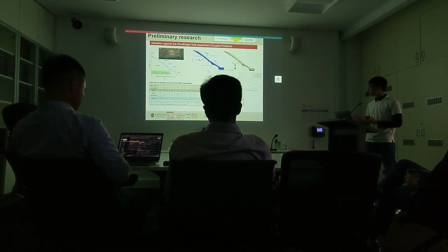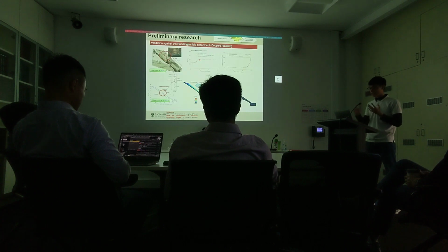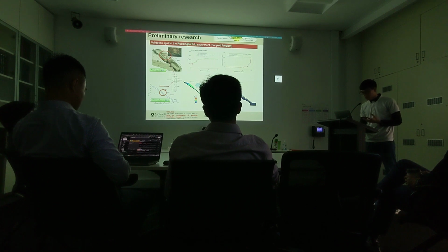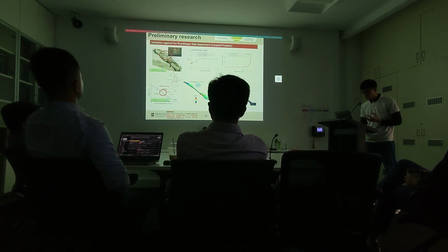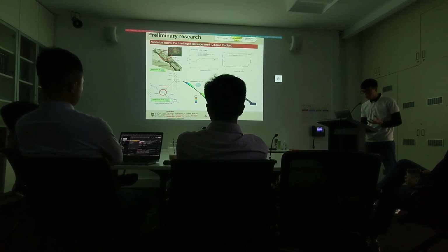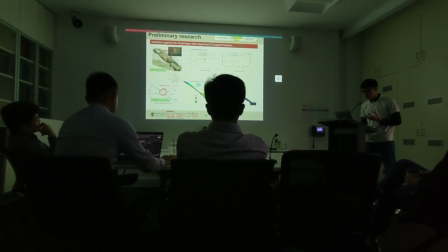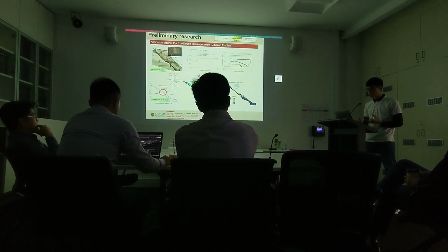The parameters here basically help us calibrate the soil water retention curve, and this is our result that we get after the rainfall, and then we have this collapse, and we compare with the experiment, we compare with the sensor on the field here. So in here, the green line represents the HBX solution, the red over here represents the sensor that you see over here, and we also capture the displacement evolution.